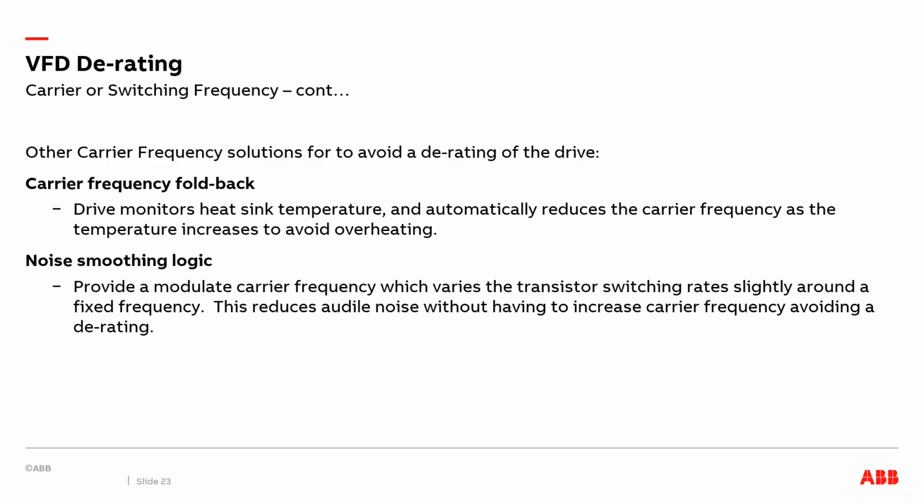Also, there's a noise smoothing logic that's built right into the drive. What this noise smoothing logic does is provide a modulated carrier frequency, which varies the transistor switching rate slightly around a fixed frequency. This reduces the audible noise without having to increase the carrier frequency, which will then avoid a derating.